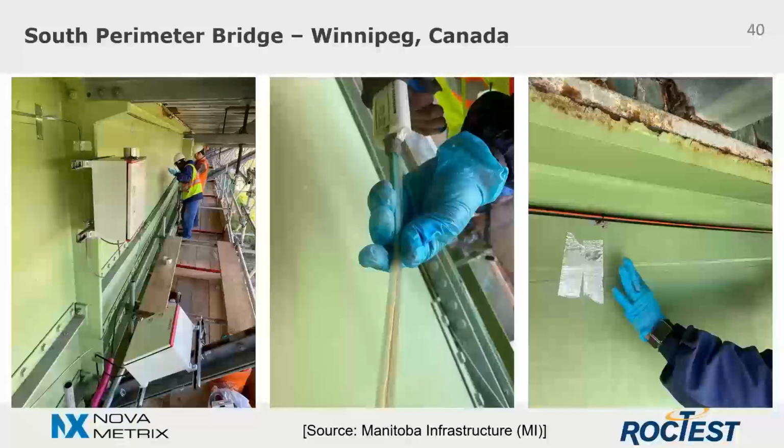Okay, here we can see the strain sensor installation. The surface needed to be clean, and the sensor was glued directly on the paint. After bonding the sensor on the paint, the sensor was protected using a special tape for humidity and impact protection.